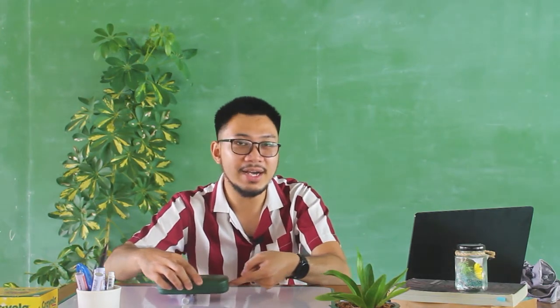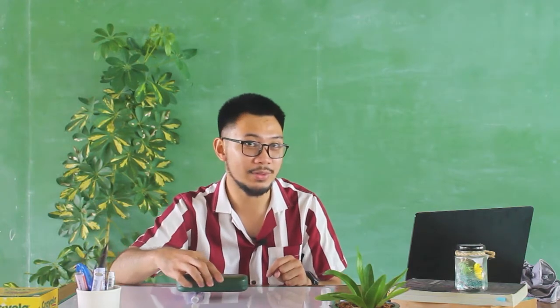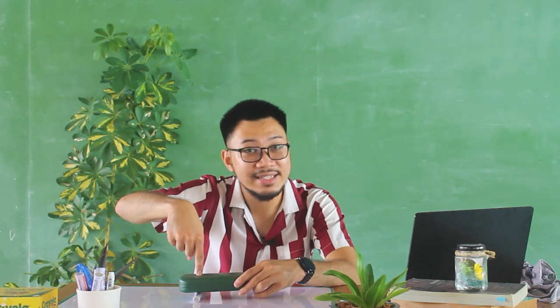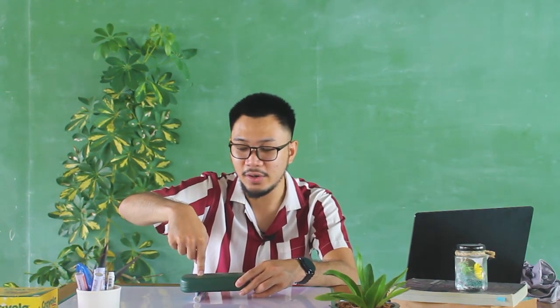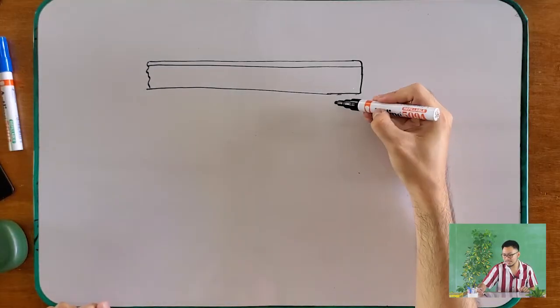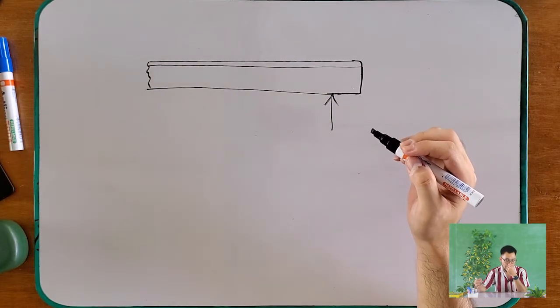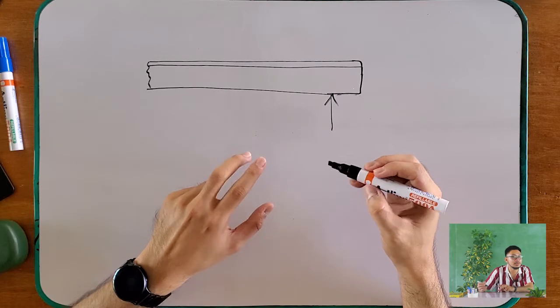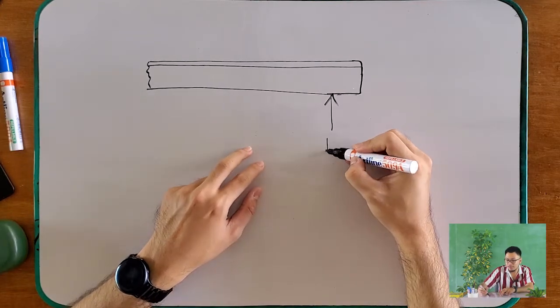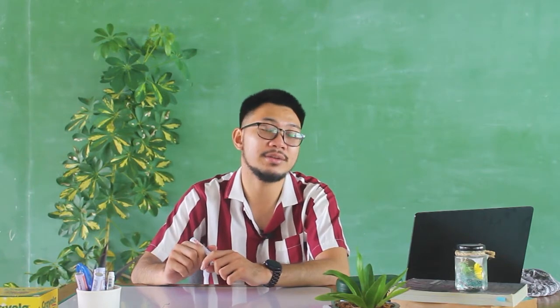So, pwede ra siya maka-freely og lihok sa atong horizontal nga component. But, kung diri ko nagbutang og force, iya gi-restrict ang atong vertical nga movement. So therefore, this kind of support, ang imong roller support, only restricts your Y component nga force, but it doesn't restrict your X component nga force.